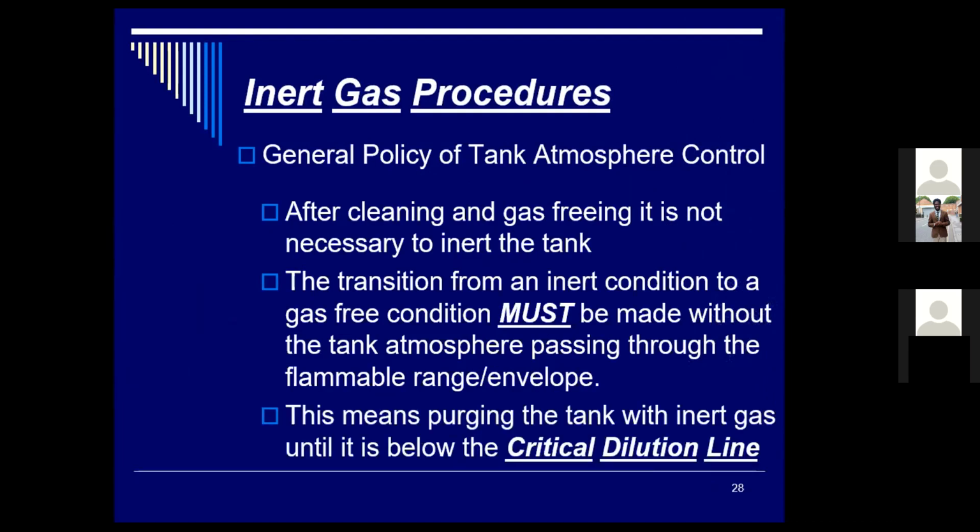So here, after cleaning and gas freeing, it is not necessary to inert the tank. The reason is, when you clean the tank and gas free the tank, you might have to maintain the tank, repair the tanks, check for cracks, or check the suction bell mount of the pumps.